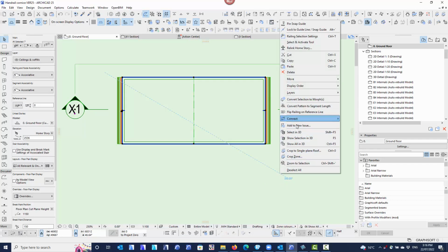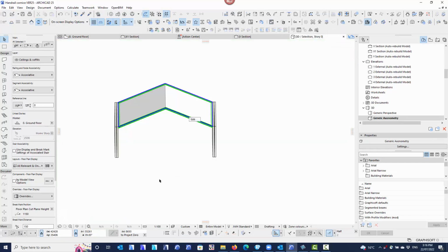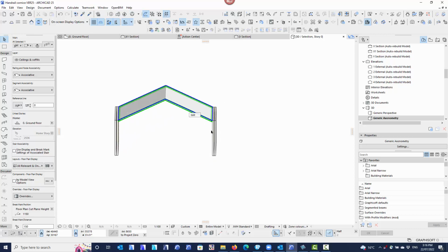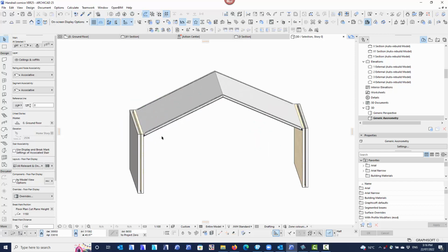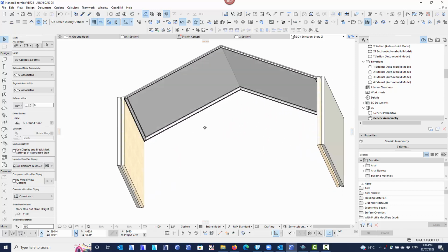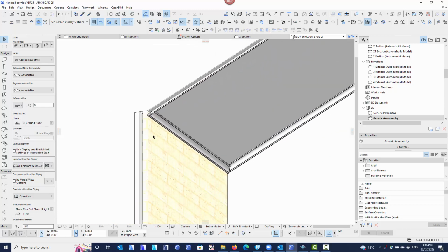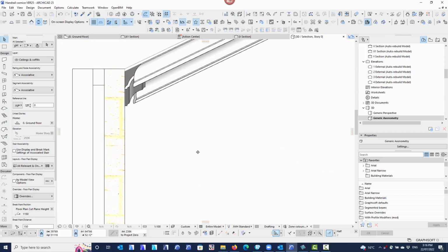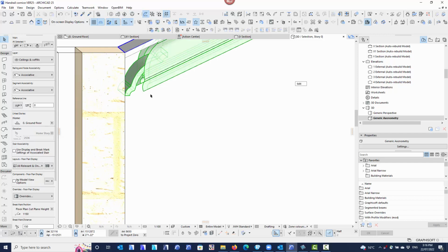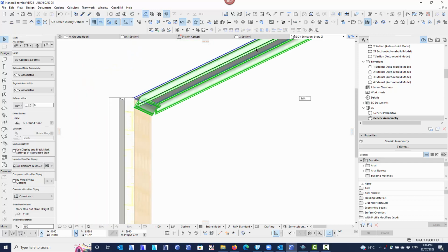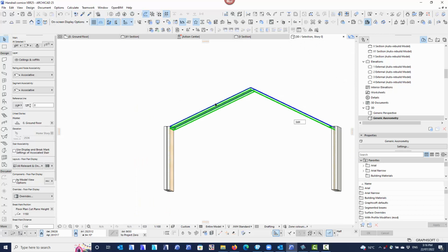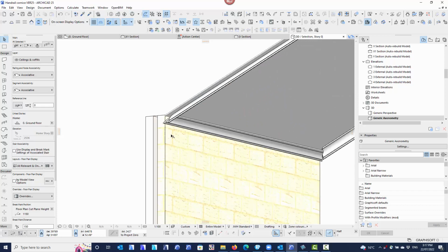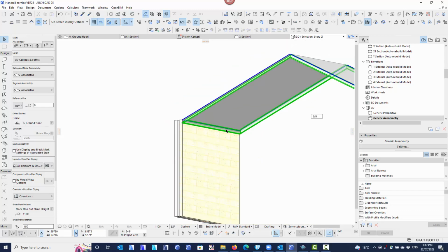Again, look at that in 3D. And now I won't need to adjust anything because it's associated to the correct things. The other thing is make sure you turn the wall layers off and just work with the ceilings. Then it has to associate to the ceiling. Now, all looks pretty good, except we've got the same problem here that we had before, where the cornice, this edge one, is not rolling. It's picking up the rake of the wall automatically, so it knows that it's raking up the ceiling there, up the gable, but this edge here is not.